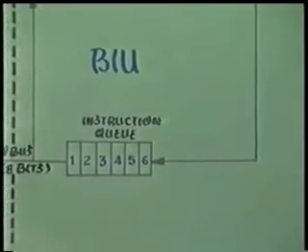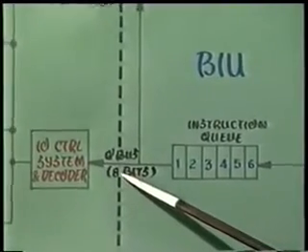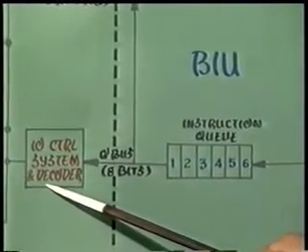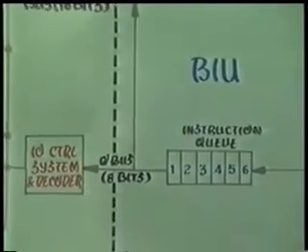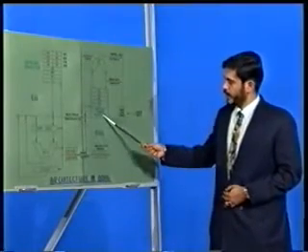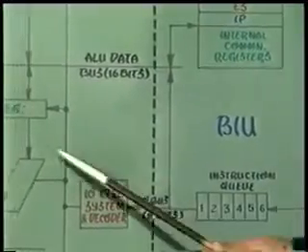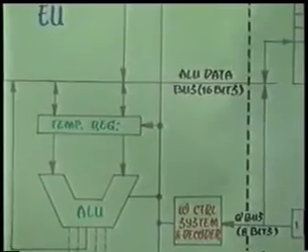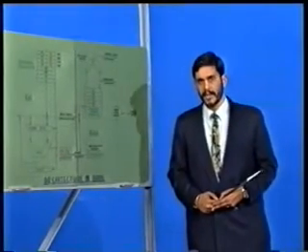These instruction codes are further transferred from the queue via the queue bus to the decoder in the execution unit for further decoding and execution. The internal communication registers and the temporary registers are used to store the various intermediate results during the calculations in 8086.